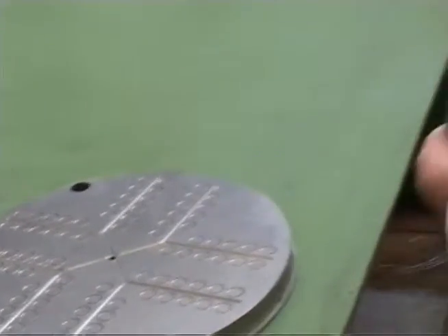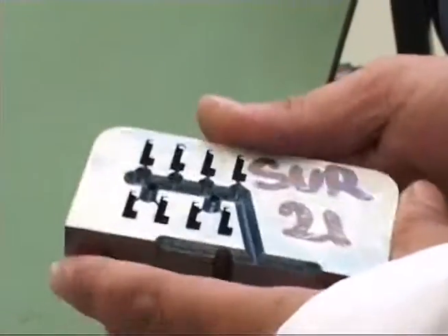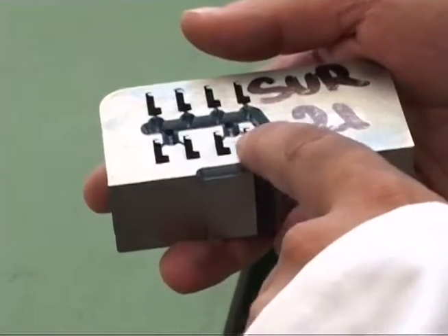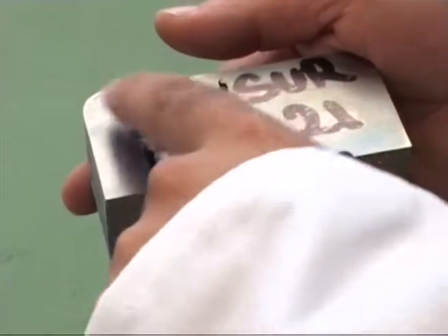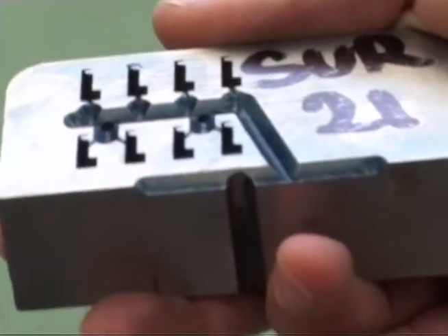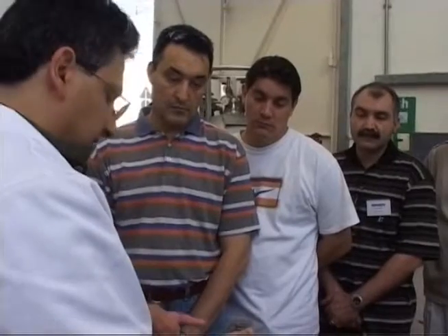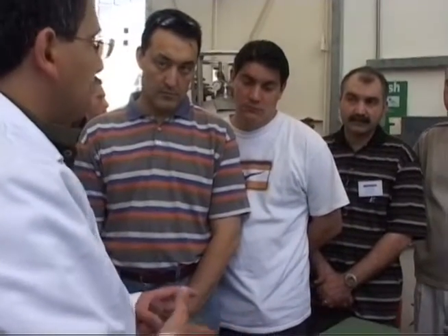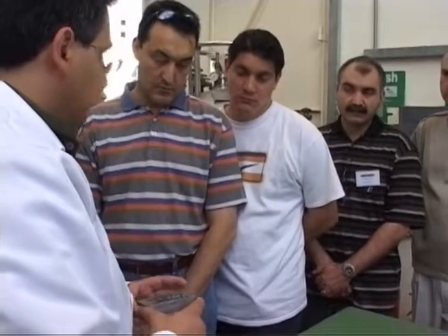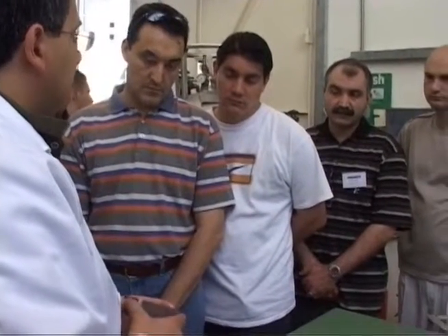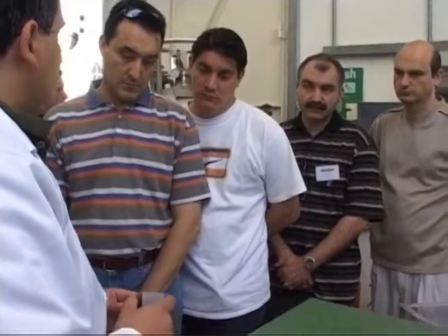In the other case, we have a small component whose important surfaces are a series of cavities. In this case, blanking the holes would render nitriding useless because these are the surfaces which we want to protect. So this type of component is suitable for gas nitriding, and plasma nitriding should be avoided.